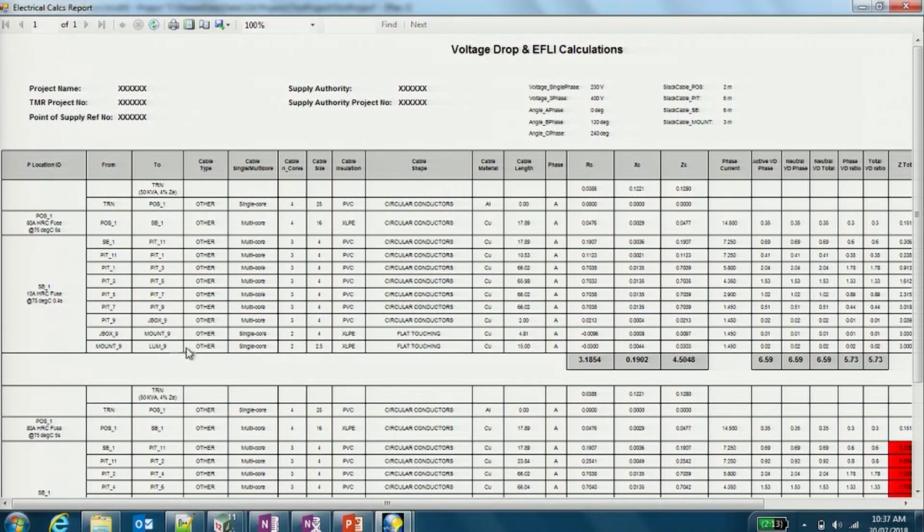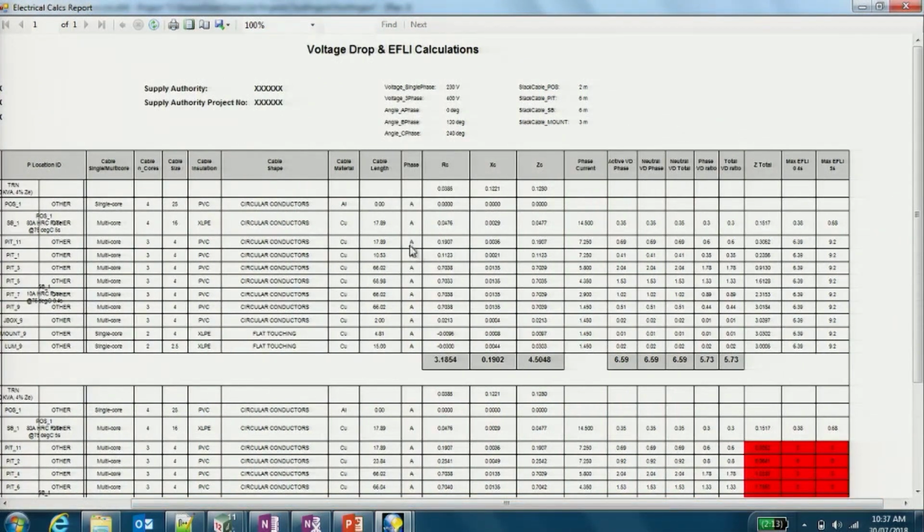So this is the worst case load calculation, which they do now, and then it'll calculate all those values for you. So now that's done for you. The electrical engineer or whoever's RPEQing it will need to verify that, make sure everything's right.